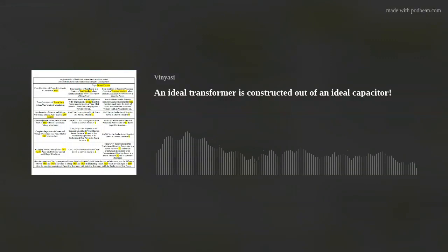I forget what he calls it, but there is a patent available for us to view. It's an elevated plate, covered with a dielectric, and it goes down to one end of a capacitor. The other end of the capacitor goes to ground, and then he takes a parallel connection to either side, the two terminals of that capacitor, to go to a pulsed load, in which he has a switch, like on a ratchet device, turning on and off to pulse the discharging of that capacitor. Meanwhile, it's charging up at a constant low rate.